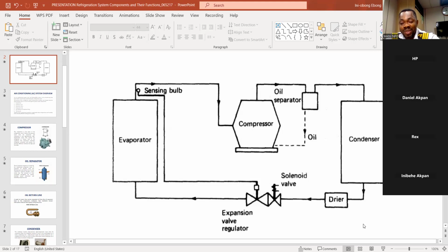For you to be able to test this, you have to use your multimeter. You see some of the people on the roadside, they will use a wire to spark and say the capacitor is working. I don't actually believe in that because you cannot factor out what the figure is. So if you calculate this, you should be able to know that if the figure is below or above this range, that capacitor is bad, so you simply need to replace it. For you to know this, use your multimeter and check it.